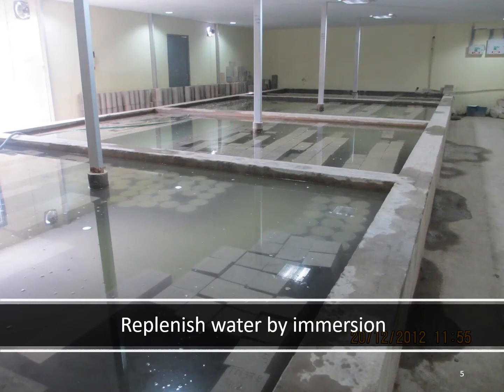This is the example of replenishing water by immersion, which you can generally observe in a laboratory at any construction site or even in colleges, where the concrete cubes which are cast are allowed to cure for 1 day or 3 days or 7 days or 28 days, depending upon the age required to test those samples.